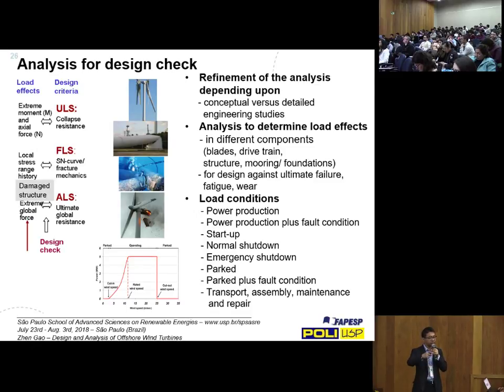Normally they operate in normal conditions with rotating wind turbines. But you also have issues with faults, and then you have to shut down the turbine. And you may also have issues with grid loss, and then also have to shut down the turbine. These occur frequently, so you have to consider them during the design analysis.